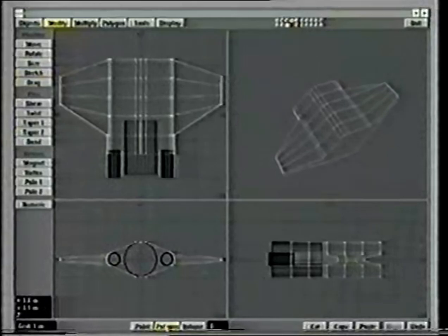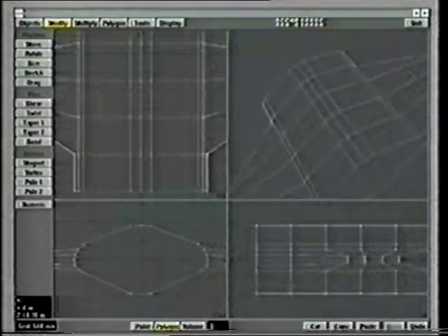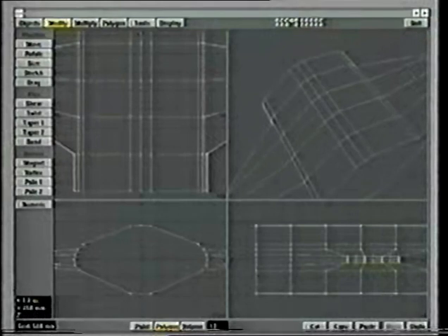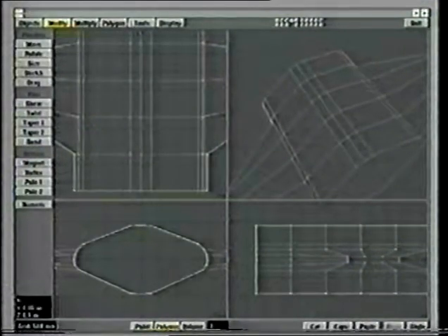Now, what I'm going to do here is remove the polygons that are on the wingtip, and I'll show you why. When using metaform subdivide on any type of shape, if you remove polygons completely, the subdivider will attempt to turn that area into a circle. And I'll show you what I mean. Let's just cut those out, and obviously as we're playing with the subdivide here, we need to remove any polygons that are greater than quads.